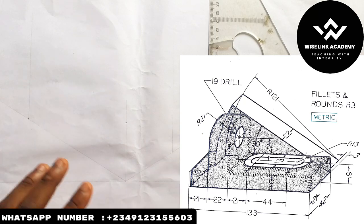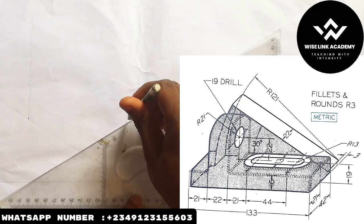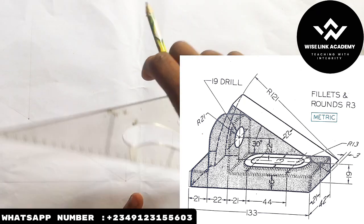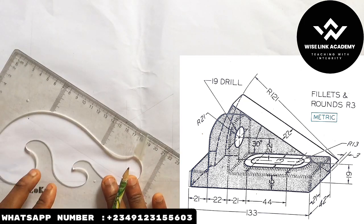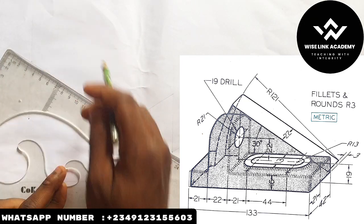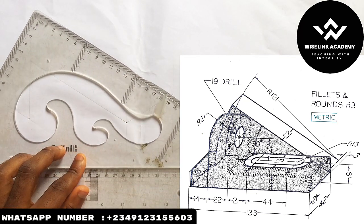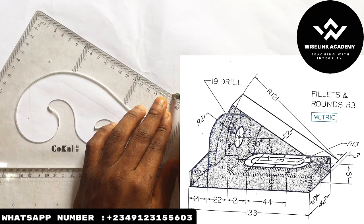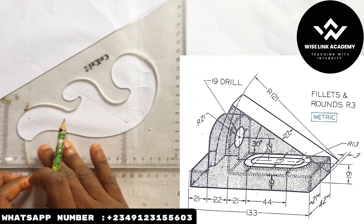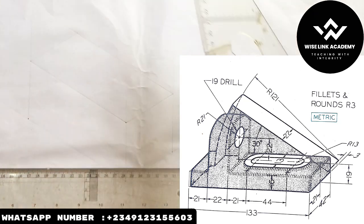Alright, from here now, I'll use this to produce a box. How? I'll take my t-square this way. I'll connect this point here to this line I just drew earlier. Next, I'll take this one here and connect it with this. Next up, I will take my t-square upward, take this one here, and connect this one to this. Then I'll take my t-square the other way around and link this one to the line I just drew. So this is a box.